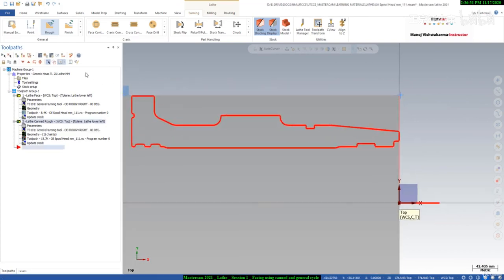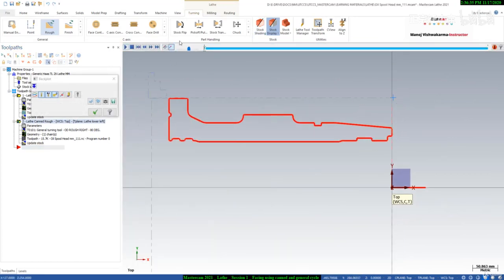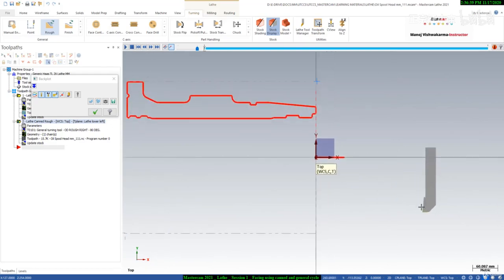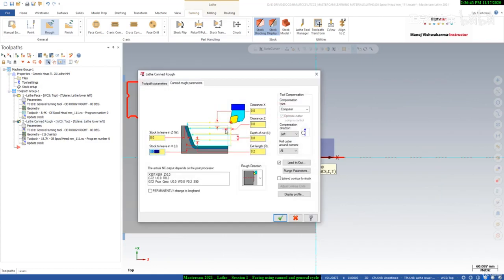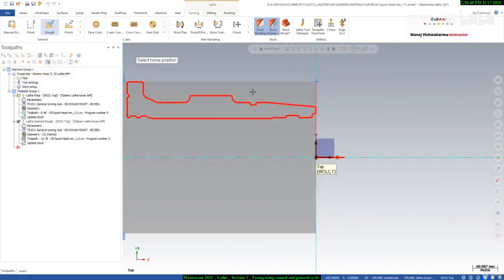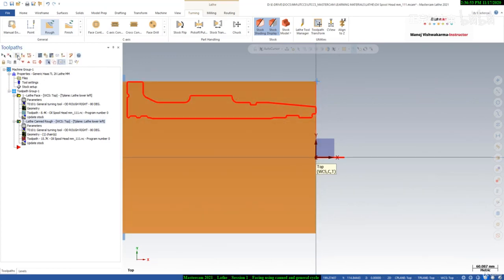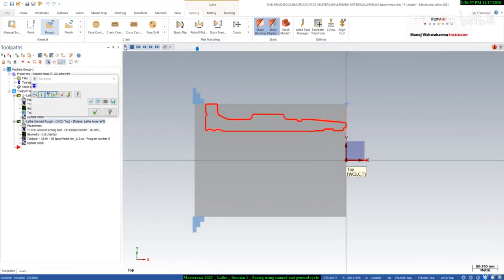So you can see we have created the canned cycle facing toolpath. So you can see this tool is moving from here because we forgot to change the home position value. So we'll go to the toolpath parameter, and here we will say user defined, define the position from here. Okay, and then say regenerate, and you can say backplot, and then say play.